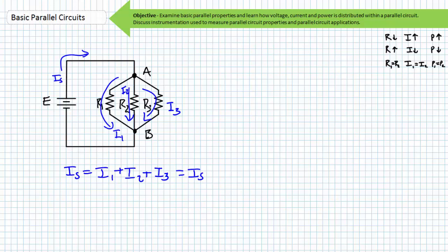To measure source current, one would have to turn off the power supply, break the circuit, and insert an ammeter, such that all conventional source current flows out of the power supply positive terminal into the ammeter, and out of the ammeter and into node A, which, if you think about it, is the trailhead for 3 separate trails. In this case, all source current, regardless of its intended destination, must pass through this single hoop, and there is no way any current can sneak around, under, over, or squeeze by the side of this ammeter.